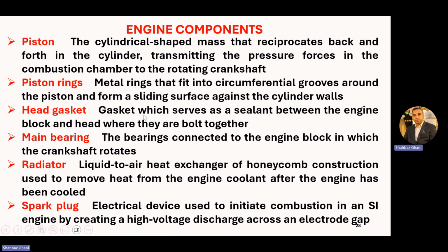Because when you machine any metal surface, there are some allowances, there are some tolerances. So to cover those allowances or tolerances, to fill the gap, you need to have some gaskets. So when you have a head gasket, the head and the block are fastened together, you place a sealant between that gasket, okay?